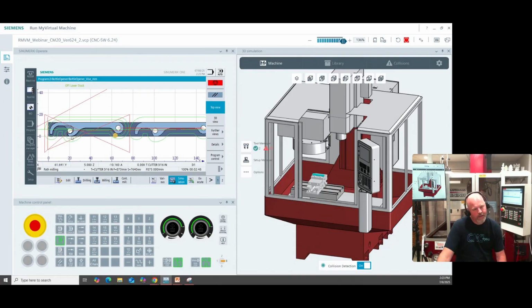The only thing I don't know for sure is that I might have to play with one that has a little bit heavier cut in here. So we might have to slow down the feed rate on that feature. We can actually do that right inside the cycle. A lot of people don't realize that. So we'll give you another little pro tip here.